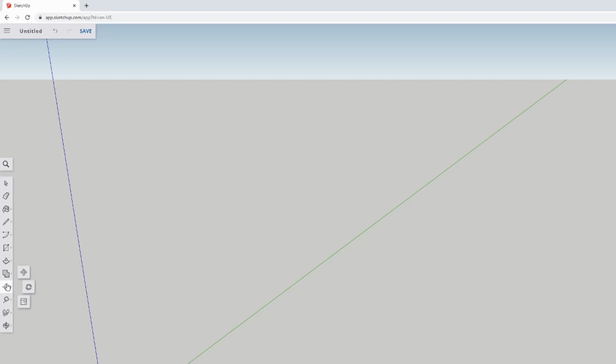The move tool, this is extremely useful, and this is one of the key components that I go to a lot. Obviously, you want to be able to move your piece around. When I create a compiled component, I tend to draw small pieces independently and then I move them to fit into place. This allows me to take a 3D drawing and create an exploded view of it. You tend to see this a lot in diagrams or part comparisons or part lists for various machinery.